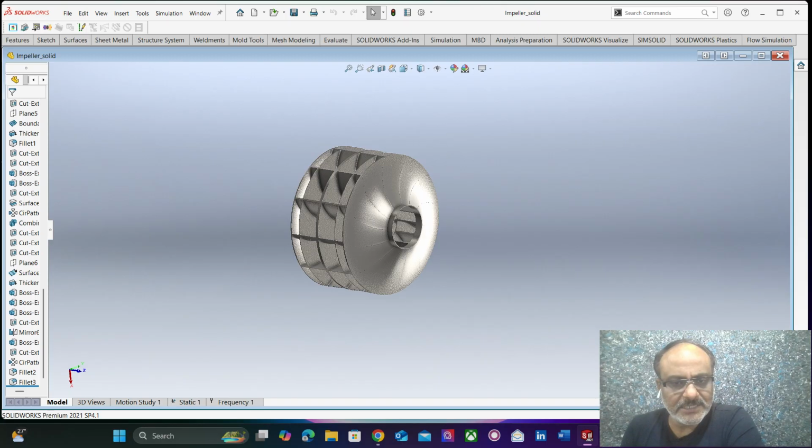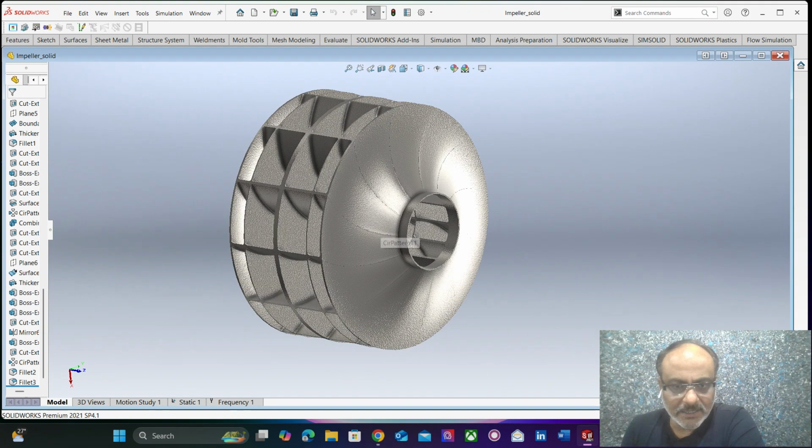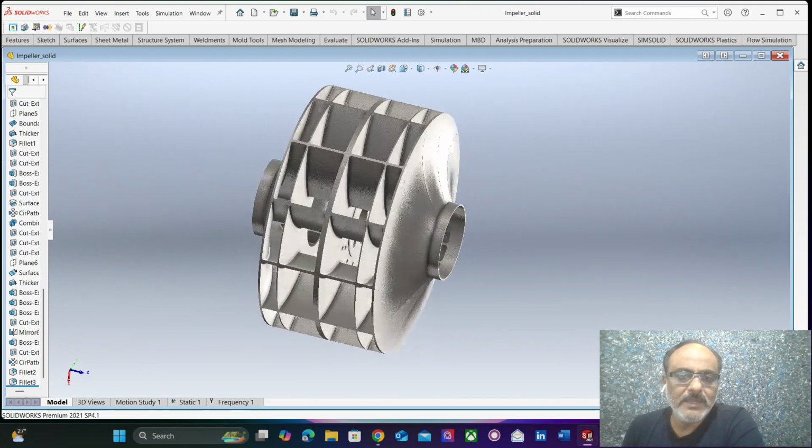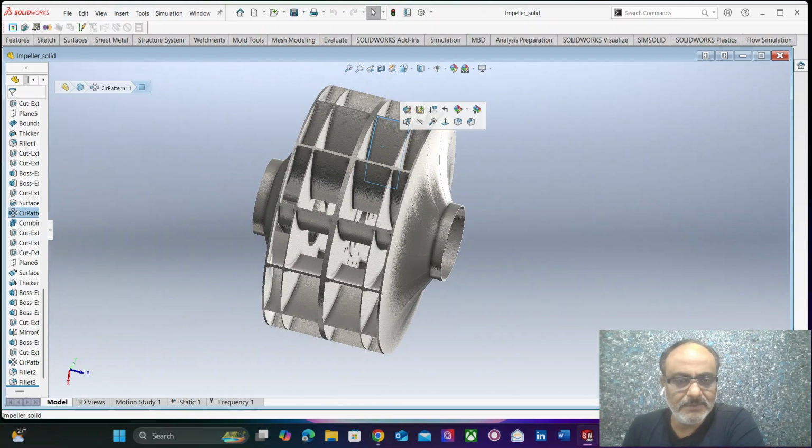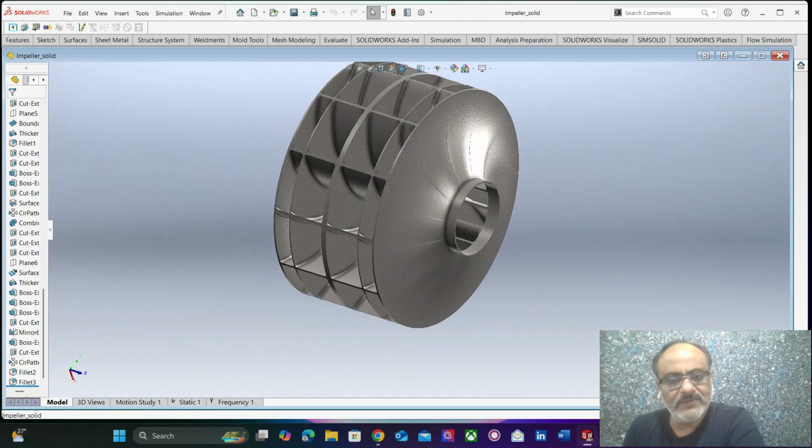And when the shaft rotates at 800 rpm, it swirls and takes a thin layer of air which is bounding the shaft, and it sucks it inside the impeller, and then it radially distributes it through the openings. These are the blades, the radial blades, and through these openings, the air which is sucked from the shaft line gets radially distributed.